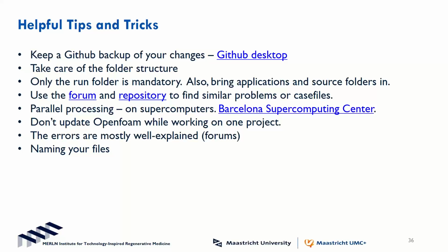Naming your files, again, is very important, but that will come automatically because you have to be very precise in what you name your files, because OpenFOAM only recognizes a certain name of a file and where the file is placed. One thing you can also do to check if your mesh is okay is use checkMesh. It tells you finally whether the mesh is okay or not okay, and what the problem was. So after 50% of the work is done, you can use checkMesh and then know that you're good to go to the next step.